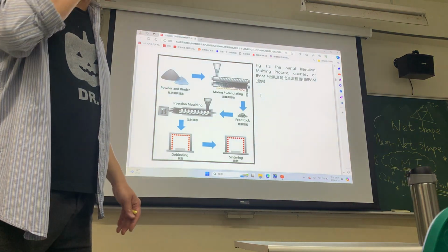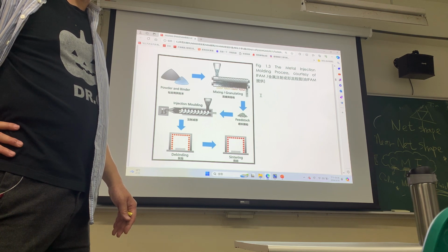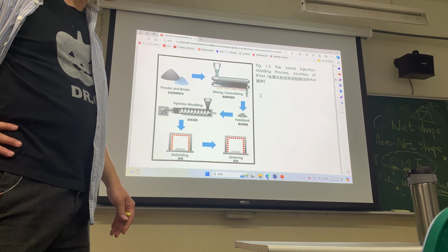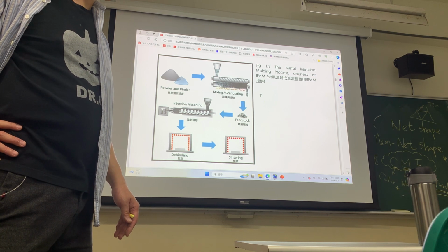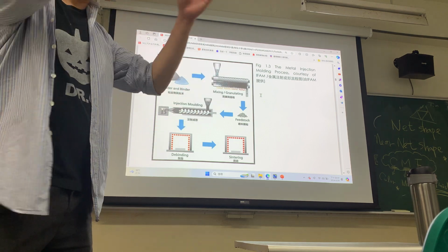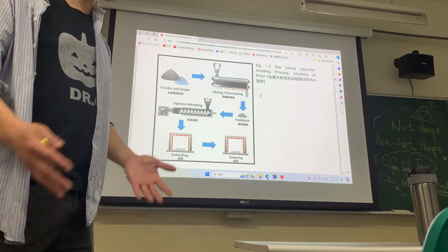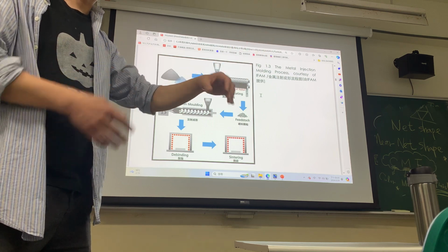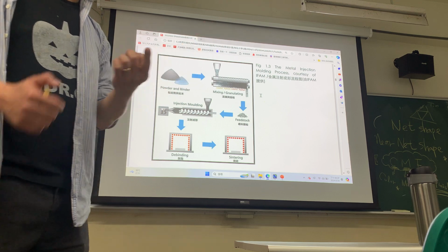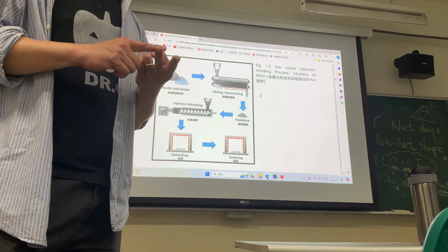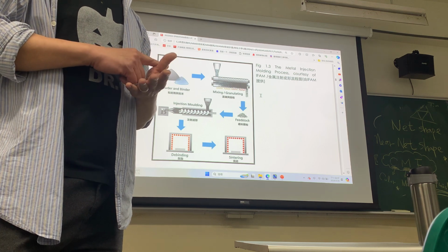Just a moment ago, the professional team asked me, should we do titanium powder? I said yes, but sintering is difficult. But injection molding is easy. We can do the adapted material. It uses the same mold. Why? Because this is the same as plastic. We just make a different feedstock, a different material feedstock. For example, titanium, stainless, iron, copper, nickel.